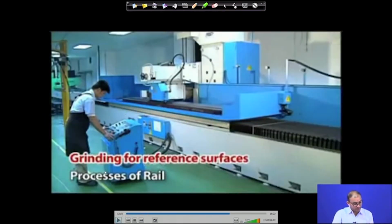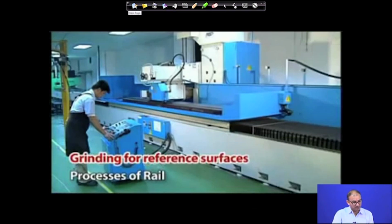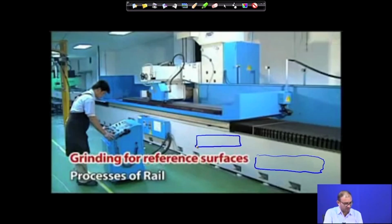Then after straightening you have to create a reference surface here. Now, what does it mean? Consider that you have one block with a very odd shape. This is the surface, and your objective is to create a perfect rectangle out of this. So, what we generally do is first a machining operation to remove this layer, and then a grinding operation. Once grinding is over, you have to mount this thing upside down.